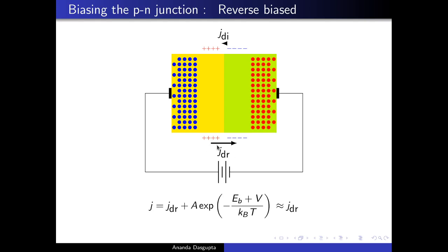Well, actually, even for a vacuum diode, you did get some current. Some electrons were adventurous enough to still overcome the repulsion of a negative anode and get to the anode, but that number was much, much lower than the minority current here. So a reverse bias diode does carry some current, a very tiny amount, but still is there.